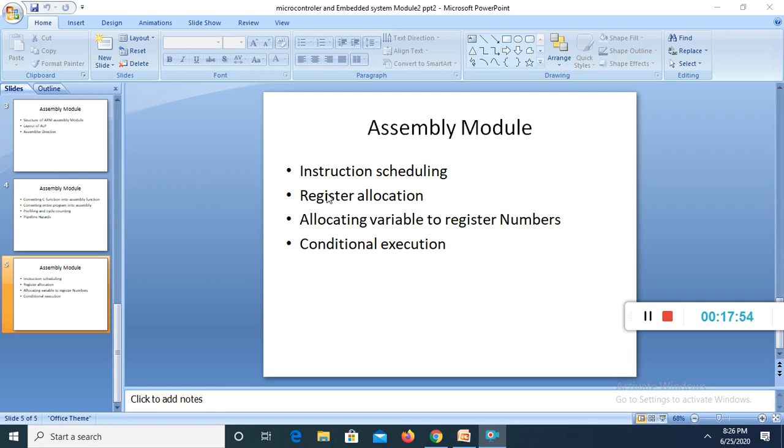However, there are some cases where the physical number of the register is important. Argument registers: the ATPCS convention defines that the first 4 arguments to a function are placed in registers R0 to R3. Further arguments are placed on the stack. The return value must be placed in R0. Then registers used in a load or store multiple. Load and store multiple instructions, LDM and STM, operate on a list of registers in order of ascending register numbers.